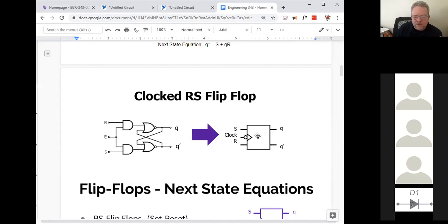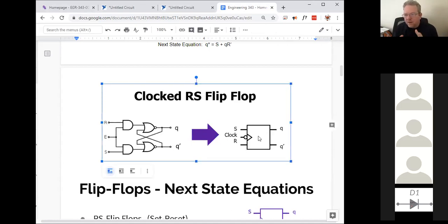So in this chapter, in electrical engineering, the standard is to take those 4 gates and then draw them as a box. We might get into what this means, but it basically means I'm only going to change when the clock goes from positive to negative. This means trigger on the negative edge. So instead of changing when the clock goes up to 5 volts, it's only going to process information on the way down. We may or may not get to that part.